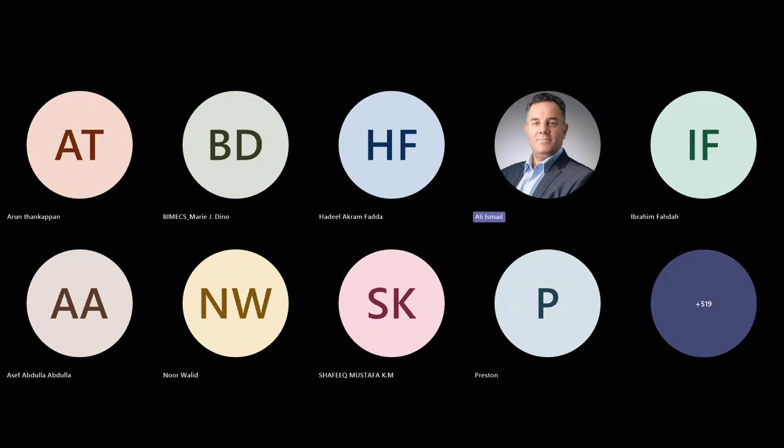Naming the levels as floors or levels, I think this is mentioned in the BIM standard, which uses a specific naming convention. And I think Aaron mentioned that you have the flexibility to add as many levels as you want, but at the end, to enable or disable only the architectural levels, floor finish level in the architectural model, or the slab level in the structural model. So if you think we are doing something not perfect, please contact us regarding the levels, and we can see if we can improve the standard.